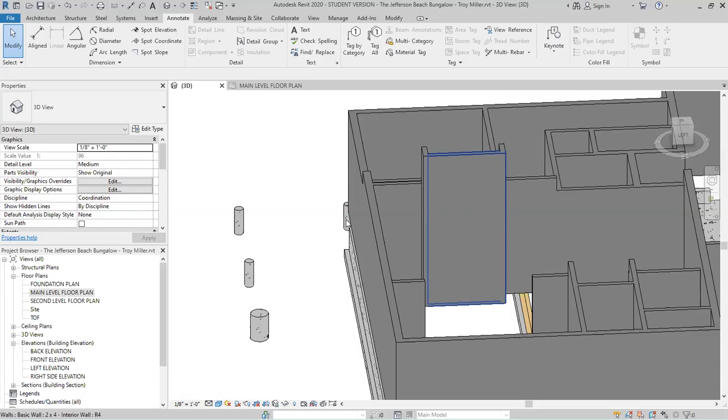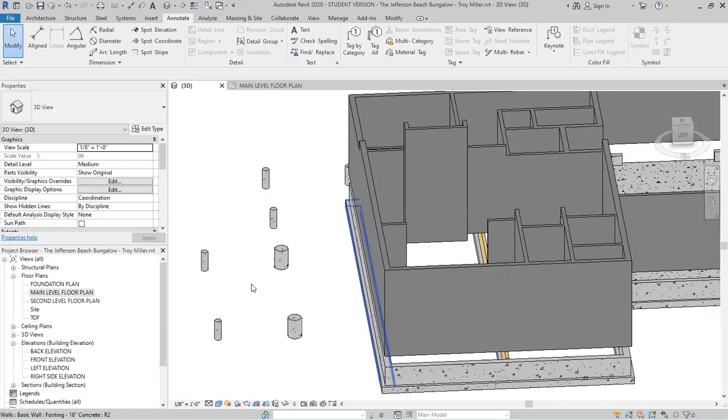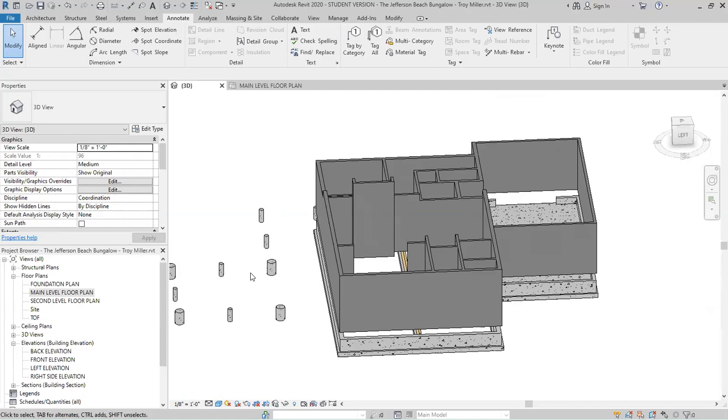And if you look at the interior elevation on this plan, which we won't right now, it actually is a gable look, and then we'd have to frame that back down. We could do just like what we did in the foundation. We could select the wall itself, and edit the profile to get that pediment or gable type look.